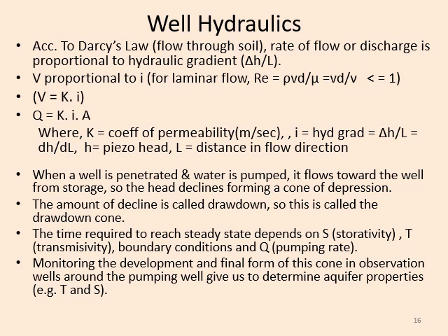We will see this in the next slide in a particular diagram. The amount of decline is known as drawdown, and if we join the drawdown points for various radii of influence, it will give a cone shape which is known as the drawdown cone.